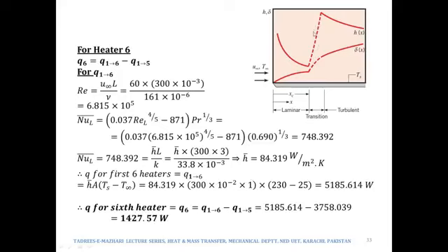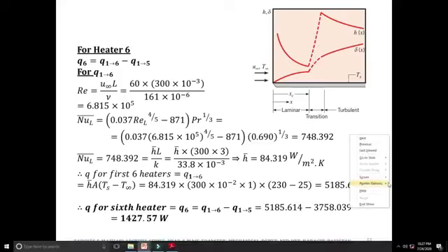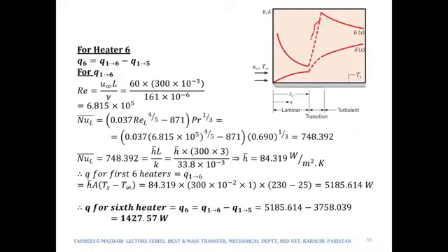It means those smaller values of H are in fact reducing the overall heat transfer from that fifth plate, and they are more in the sixth plate. The values of Hx are more in the sixth plate, therefore H bar from the sixth plate is more, and therefore the Q from the sixth plate is more as well.